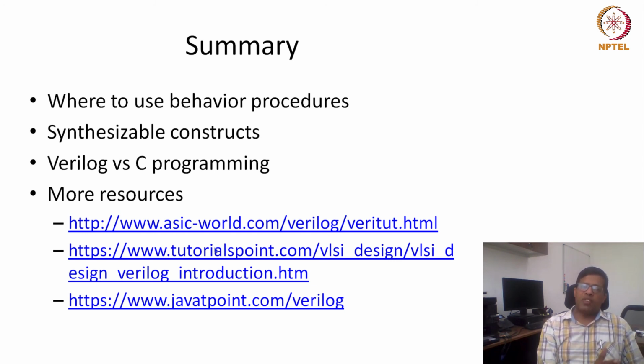But we have not preferred it in this particular assignment, because it is more appropriate to use the behavior model whenever we are modeling sequential circuits. When we are using sequential circuits, we don't have an alternative. To implement a D flip-flop or any kind of memory structure, behavior models are the most appropriate, because you have this reg type which is internally defined.